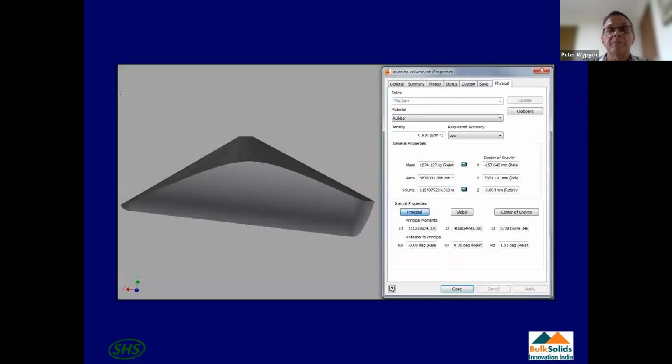So in the end, we developed a program that can apply to any blow tank system. If you can do your angle of repose testing in the lab, then you can do this quite accurately. Then you can model your system and quantify it fairly well, a lot better than just picking numbers out of the air. In the end, we achieved our objective, a 30% increase by just improving the cycle times on their system. The client was very happy because they just had to buy some airflow meters and airflow controllers, and they got their 30%. So they were very pleased.